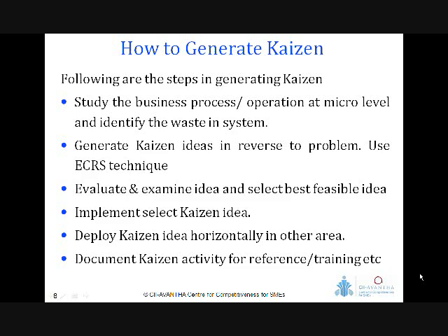Next is to generate ideas. Always generate ideas in reverse to the waste. For example, if there is coolant leakage, then the Kaizen idea should focus on elimination of coolant leakage. Generally, the manufacturing industry applies the ECRS technique for this, where E stands for eliminate, C stands for combine, R stands for reduction, and S stands for simplify.